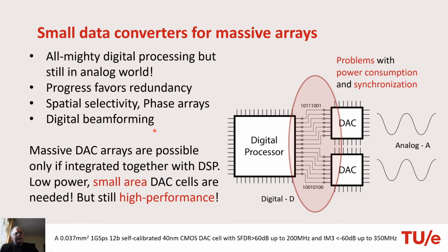The problem is that if they are not integrated, so basically you use say a single chip per D2A converter, and then the integration is on PCB level, there will be some interconnection between the digital processor and the DAC. And this will be very, very expensive both in terms of power, but also the quality of the signal in terms of synchronization. These buses will be enormous.